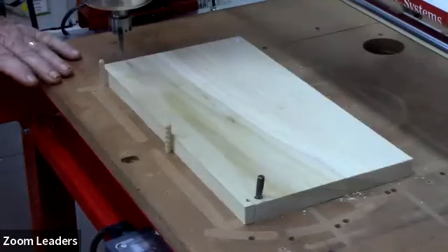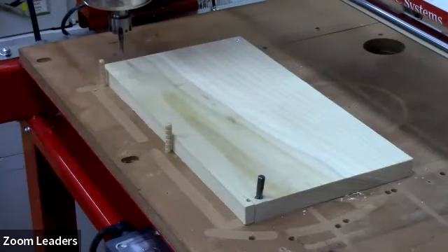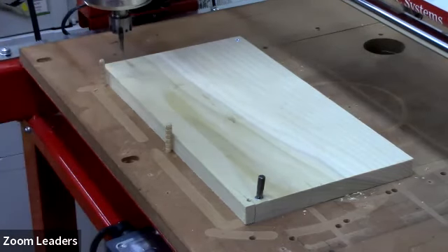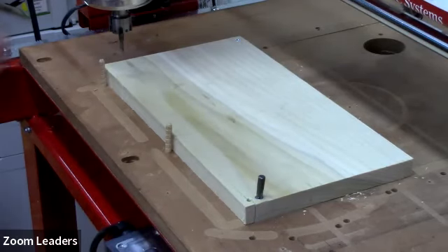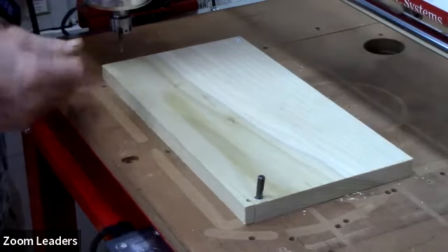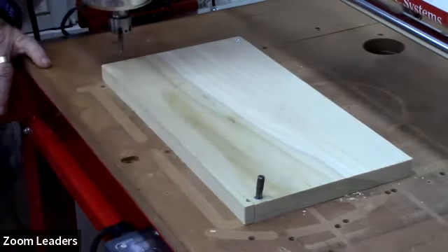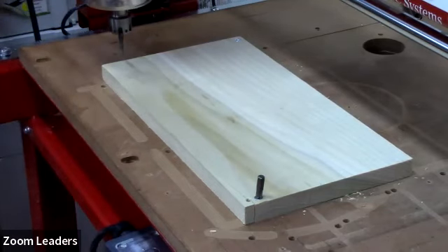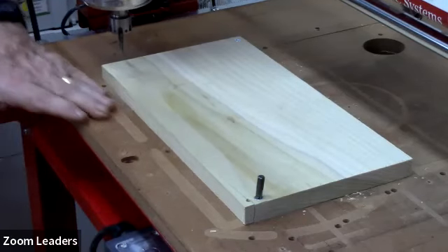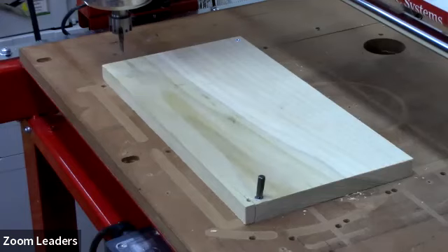Over here, to your question earlier, was, okay, how do we tell the system that we're aligned to what it's done? Well, look at that. That's nice. What I typically do is I use something like dowels that I put in holes in the spoil board that are parallel with the travel of the spindle. And that way I know that whatever I cut is going to be aligned to this edge.